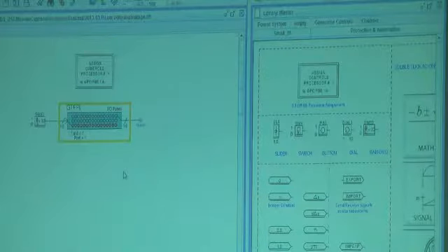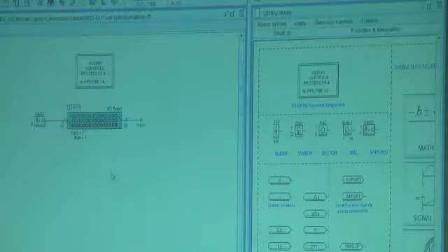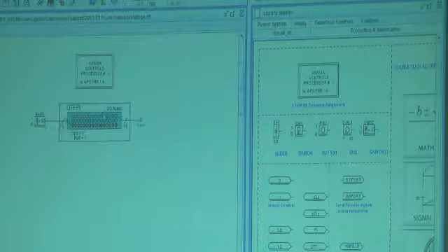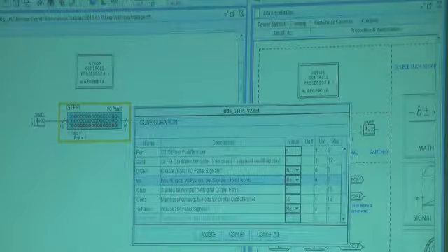It's a dry contact, so if it's connected to the trip signal from a relay coming into the simulator, when the relay trips and the contact closes, it shorts the input. So in our simulation, typically if we monitor, we'll see 5 volts or a 1 at the input. When the relay trips, we see a 0. Sometimes for protection, we might want the trip to be a 1, right? To trigger breaker opening or something. So we can choose to invert the signals. Yes or no? I'll leave it at no for now.